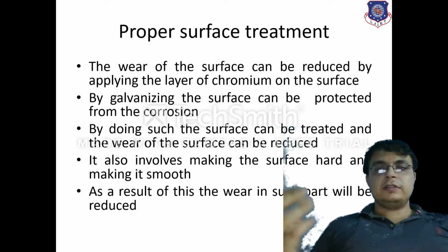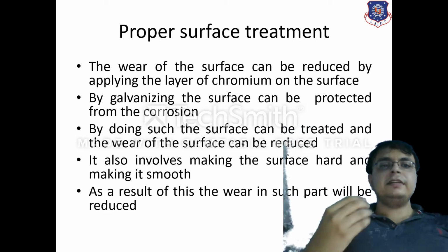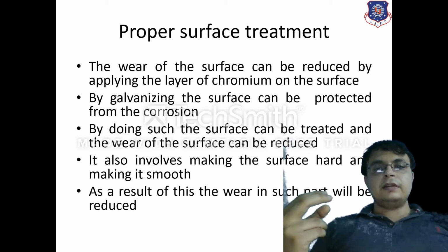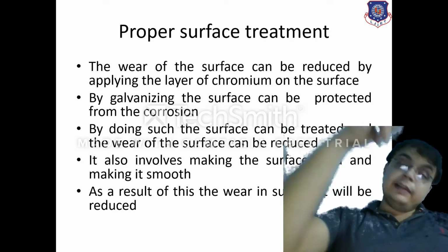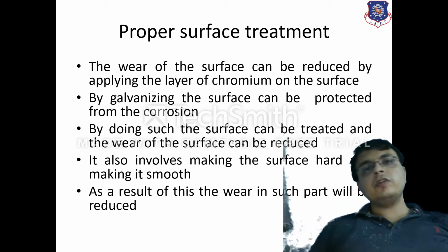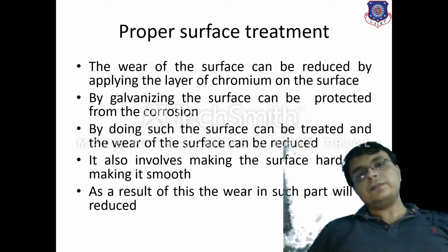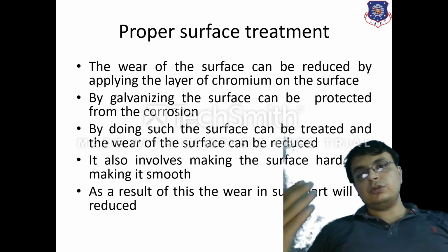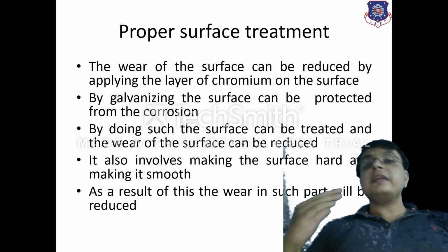So as a result of this, the surface will be hard, it will be protected from the corrosion, and it will resist the extra load. The next method for the surface treatment will be galvanization. So by galvanizing, the corrosion will get prevented.